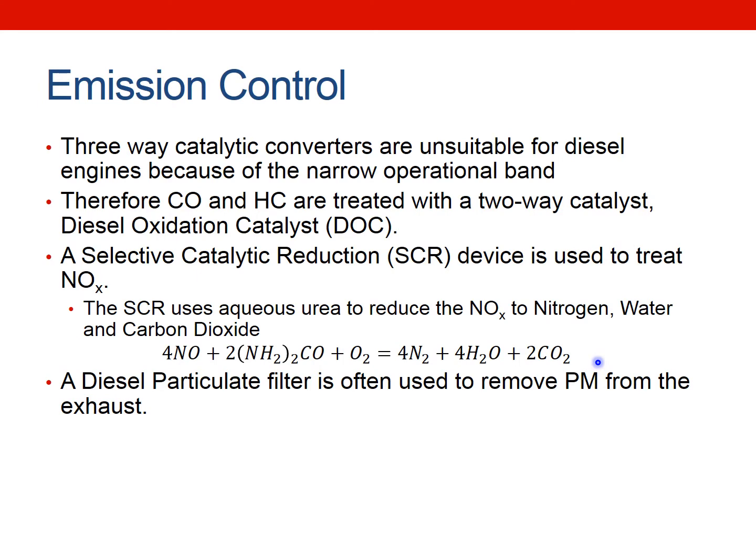However, we got rid of our CO, HC, hydrocarbons and our NOx. We also need to get rid of the particulate matter. And if you remember from the first lecture I gave, the video that showed how sooty the combustion of diesel was compared to gasoline. So modern diesels now have been fitted with a particulate filter, which is used to remove the particulate matter from the exhaust. And this is nothing really more than a glorified sieve or filter. It just catches the particulate matter.